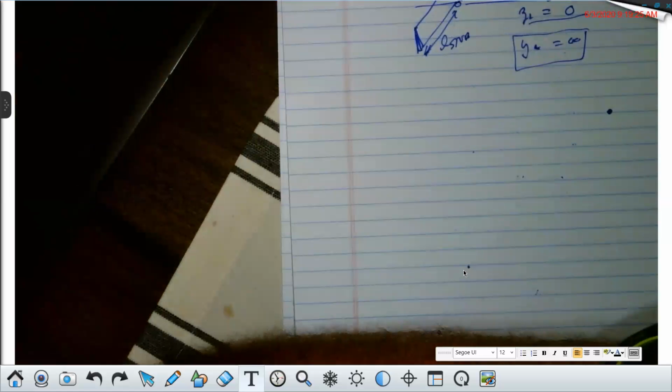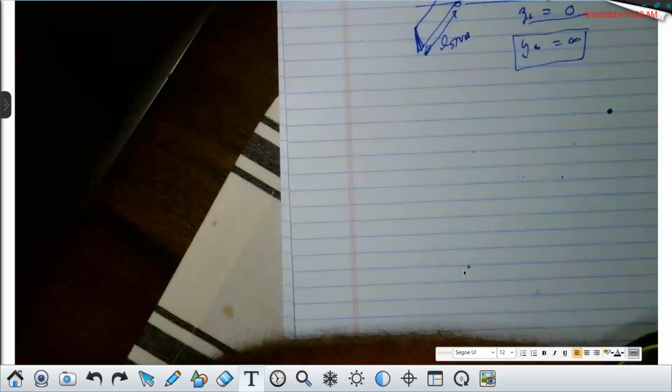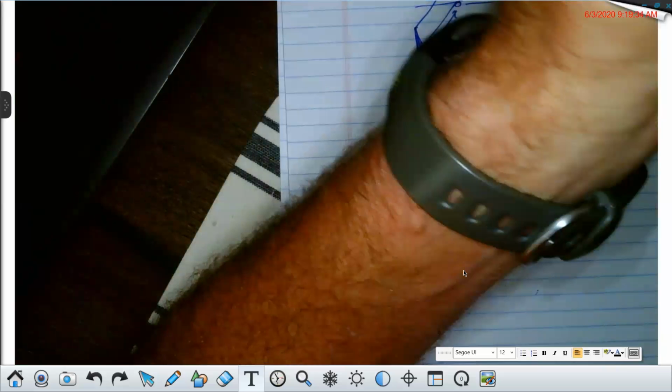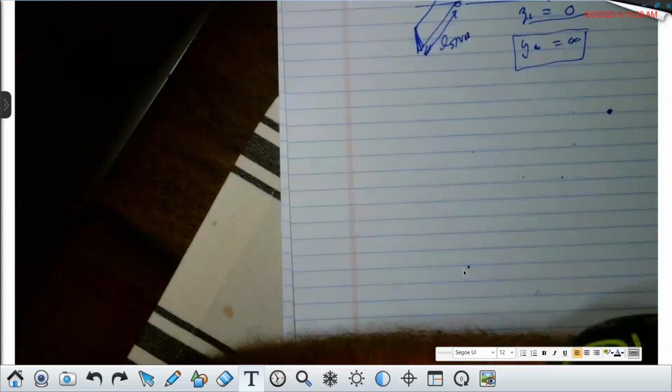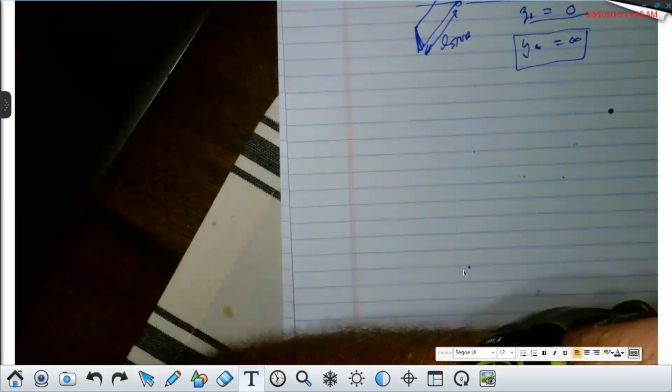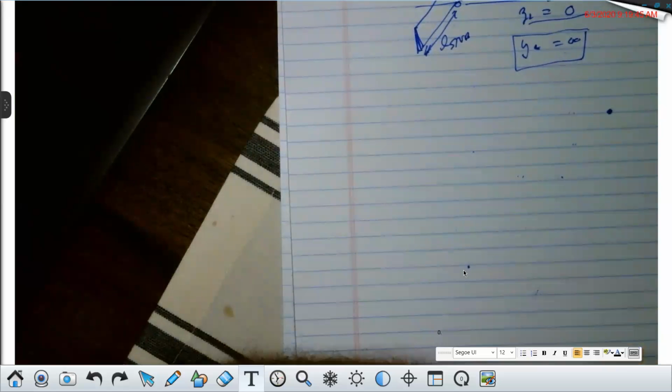And again, the key thing, be it either shunt or series, is always moving from the load until you get the point where you have 1 plus J, plus or minus something if it's impedance. If it's admittance, 1 plus J something, plus or minus JB, right? And then adding a component that will get rid of that JB or JX, correct? In series or parallel. Everybody with me, class?